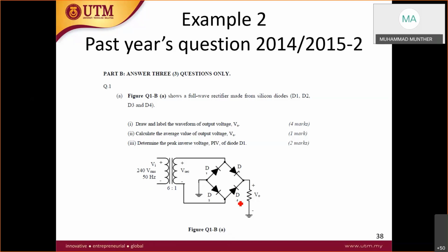It's okay, don't get confused, because when you draw in your breadboard or in your real circuit, the grounds will finally meet at the same node. In your drawing, you can draw many grounds, but at the end of the day, in your real circuit, ground will meet at the same point. So it is just a matter of understanding. Okay, thank you, doctor.